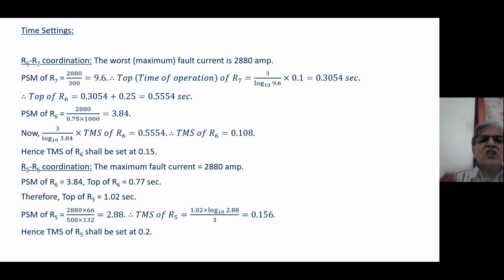When 300 ampere is flowing in primary, 1 ampere does not flow in secondary. Some 0.03 ampere excitation current is deducted and some less current will flow. But that current is so small that I can forget. That's what I'm doing. I am forgetting that small excitation current. In earth fault relays, I will not be able to forget. But let it apart. We won't be mixing two things.